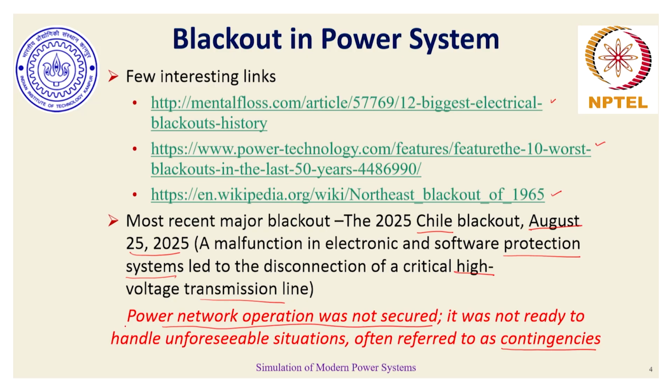It is impossible to predict that at the next instant of operation, a particular line will remain operational, because of bad weather, because of overloading, or because of n number of reasons. The network faces these uncertain events. In fact, sudden load change and sudden load drop are also contingency events. And in order for the network to not go into a blackout mode, certain corrective or control actions need to be in place so that the network is still able to sustain the impact of these contingencies while ensuring that generation and load balancing is met.